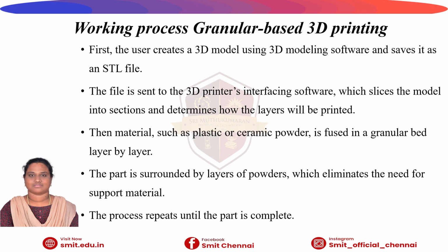Next, the working process of granular-based 3D printing. First, a 3D model of the object is created using 3D modeling software and saved as an STL file. This file is then sent to the 3D printer's interface software, where the model is sliced into thin layers and the printing path is defined.